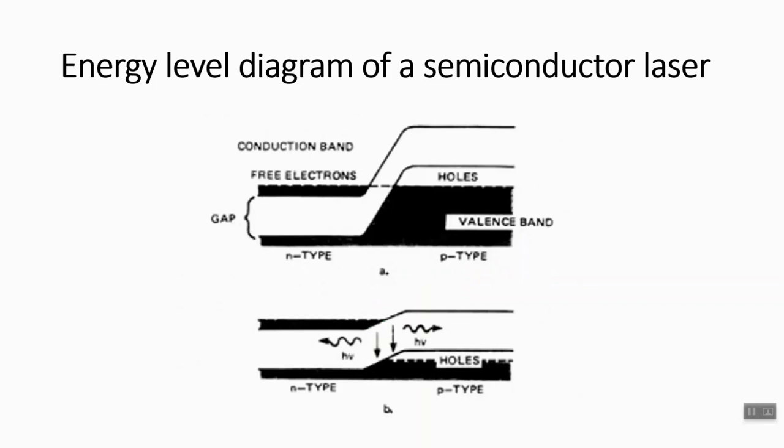When the laser diode is forward biased, electrons from the N side and holes from the P side diffuse into the depletion region where both carriers recombine. The result of recombination in direct band semiconductors is the production of light photons. Under forward bias condition, when drive current through electrical connections reaches threshold level, population inversion results and a coherent radiation emerges out. This figure shows the energy level diagram of a gallium arsenide semiconductor laser. In semiconductor materials, electrons may have an energy within certain bands.